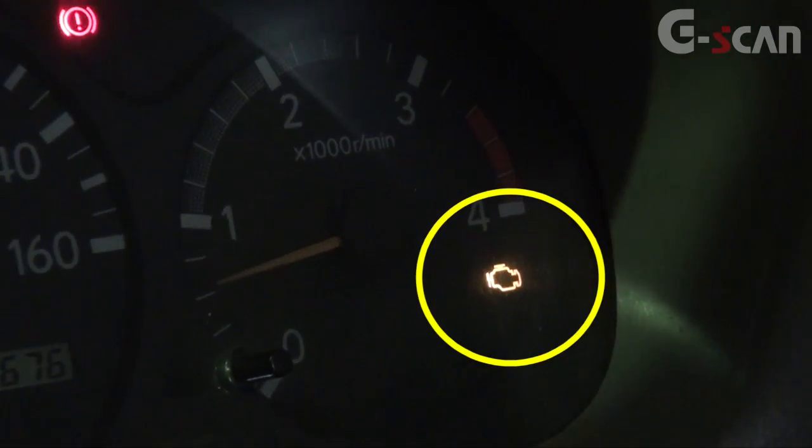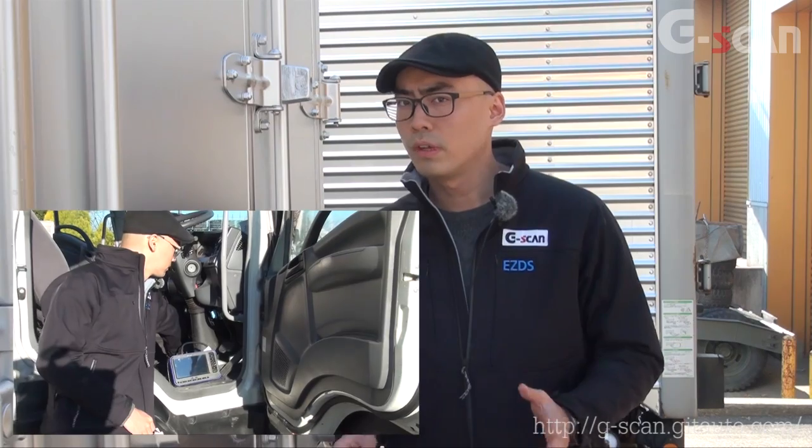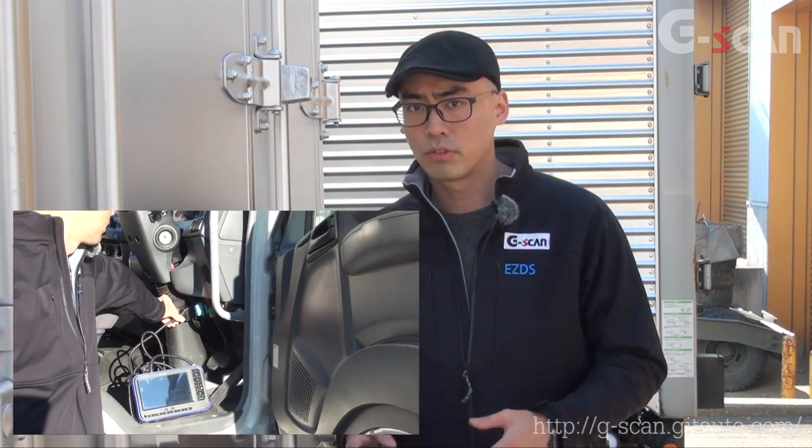Now let's talk about some basic diagnosis technique using G-Scan. When you notice that your vehicle seems abnormal and suddenly the malfunction indicator lamp comes on, what would you do? Of course, you would try to find out why the MIL came on. First, you need to figure out which system is malfunctioning by reading the diagnostic trouble code. In order to read the DTC, you need to search for the data link connector location and connect G-Scan. When you're set, you can go to DTC analysis and then read the DTC.